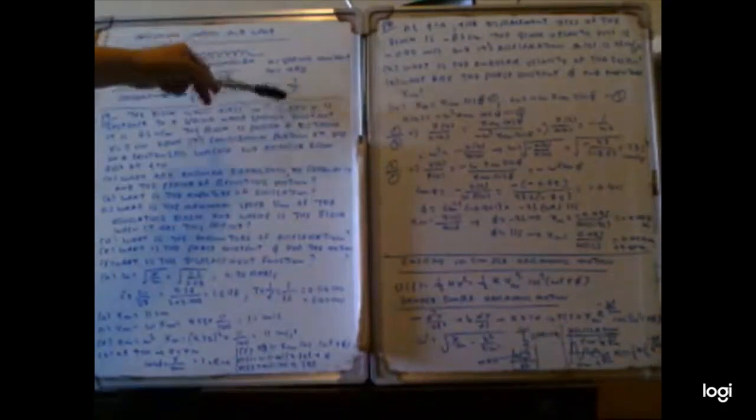Convert to kilogram by dividing by 1000, so that's 0.38. So you get 9.576 radian per second. This is for the omega. And then based on the omega, we have to calculate the frequency. The frequency f is going to be omega by 2 pi. So 9.576 divided by 2 times 3.1416, you get about 1.52 hertz.